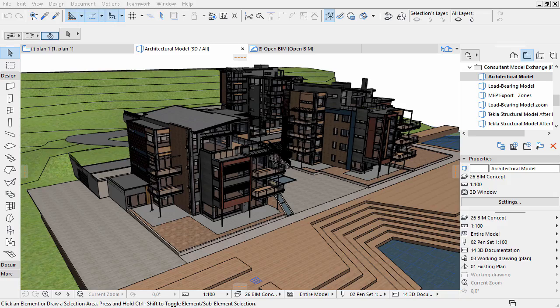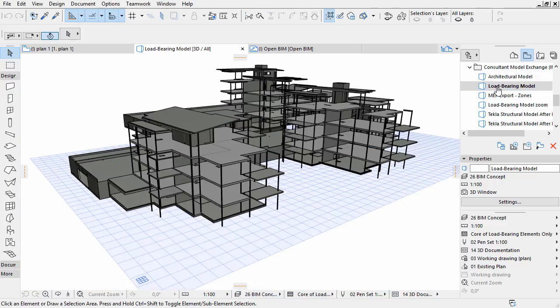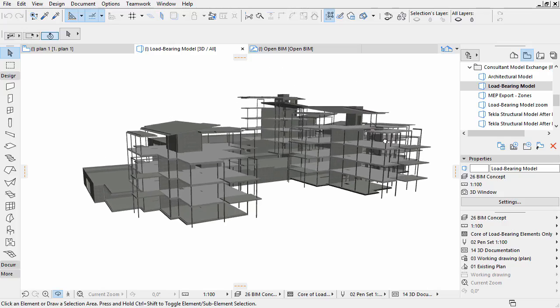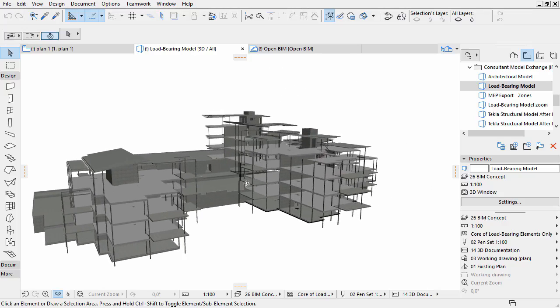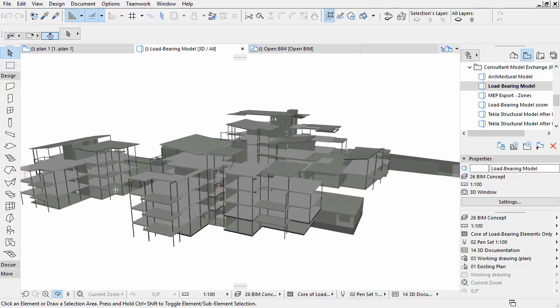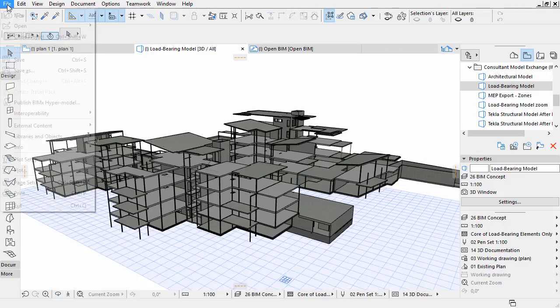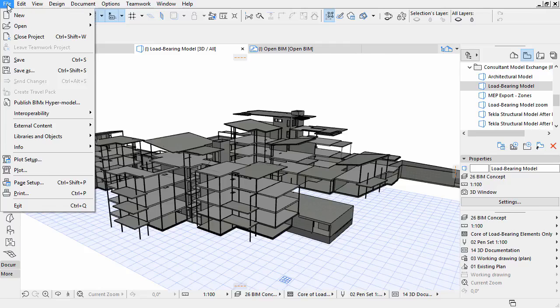For data exchange to take place, each discipline should be able to easily extract the model information that must be communicated to the other partners. For example, displaying only the structural view can be helpful when exchanging data with the structural engineer. This 3D view is easy to produce. See the settings introduced in Section 4.2. In this case, only the load-bearing structure needs to be exported.